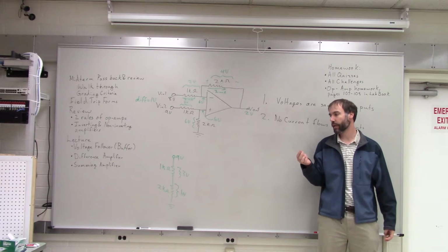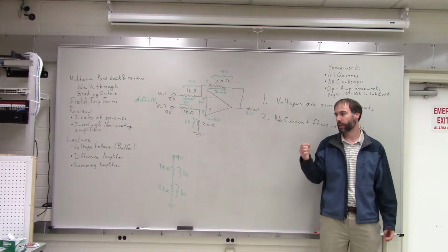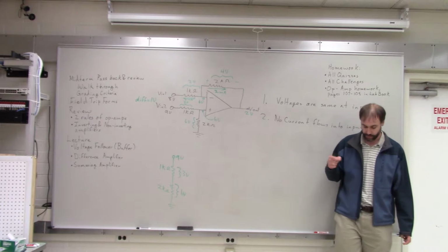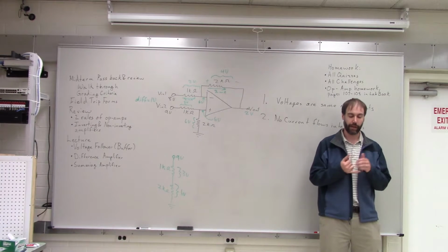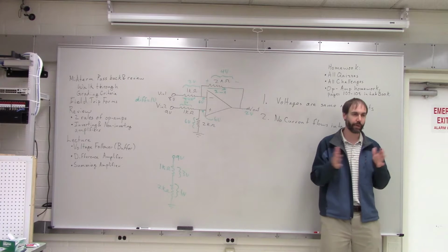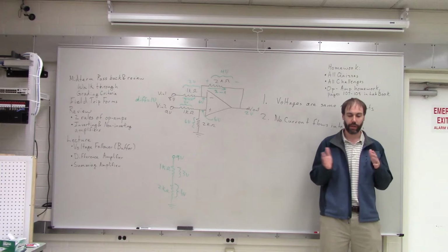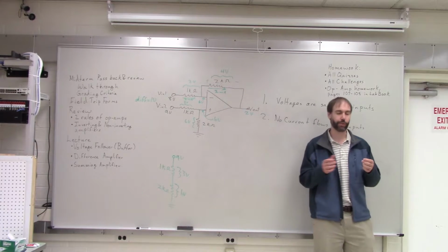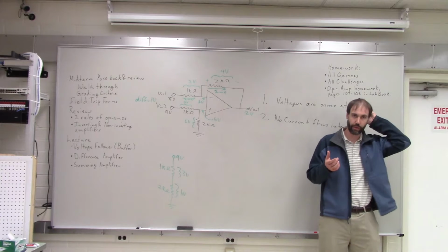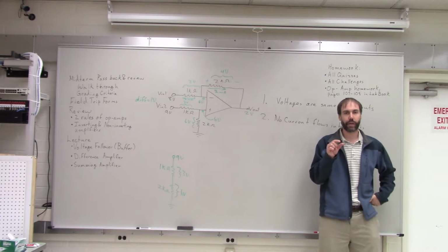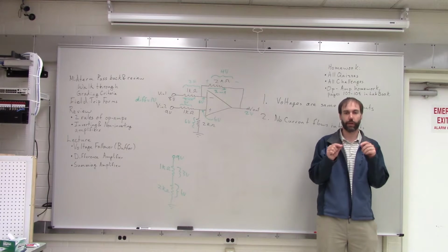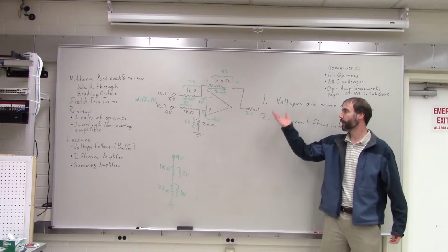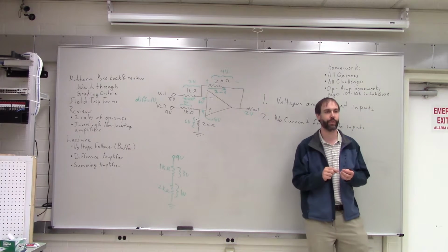It also happens a lot in sensor type settings where you are measuring a signal coming out of a sensor, either for a seismic measurement or something like that, or there are other instruments called strain gauges that are used often in engineering. Oftentimes these create small differences that you have to measure. So you could use a differential amplifier like this to just look at the difference between two signals.